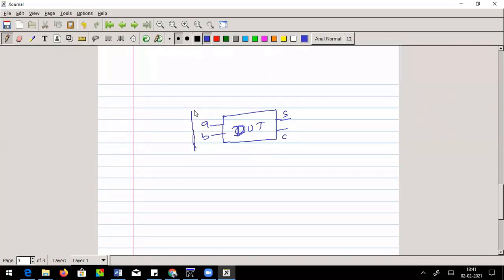the program which you write for the test bench is in no way relevant to the design. This is my design. This is my test bench. Actually, the test bench is simply to force a value to your design and check your output. Other than that, it doesn't have any role to play. Or you are not going to synthesize this test bench to make an equivalent hardware.